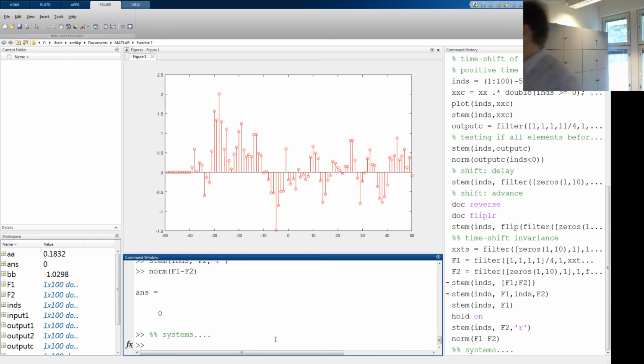you can just do the brute force and just follow the signal. So here we have x n minus 1 on this point. If there's one delay, actually 1/4 times that one, and then we have 1/4 times x n minus 2. 1/4 times x n minus 3. So basically you can get the same equation also the other way around. So it's actually a little bit easier just to read.